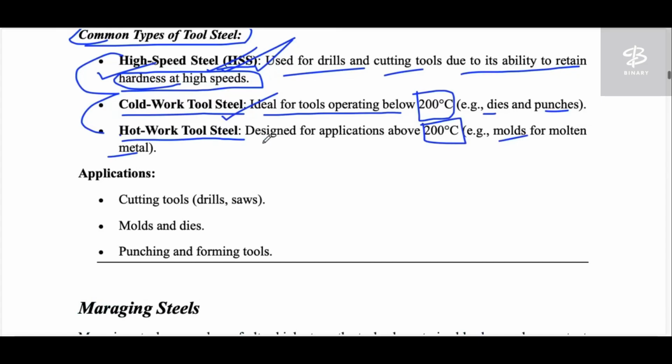For that we supply some other foreign element, which is known as lubricant, in a very water-like, milky form. It is not thick, it is very thin, with very low viscosity, which we use as a lubricant in CNC so that we can reduce the temperature of the machined component. It means they are working at temperatures of more than 200 degrees C.